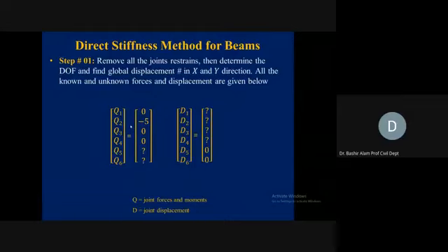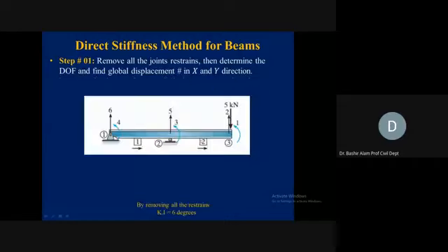Here, if you see, we have 6 displacements. The first ones were free. So D1, D2, D3, D4 were free. Let's go back to this. You see here 1 rotation is free. This one is free, this 3 is free, and 4, this rotation is also free. So these 4 displacements were free. Free means we don't know how much it is going to displace, so we put question marks.